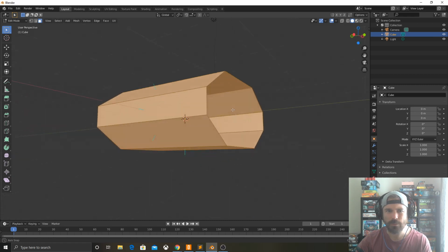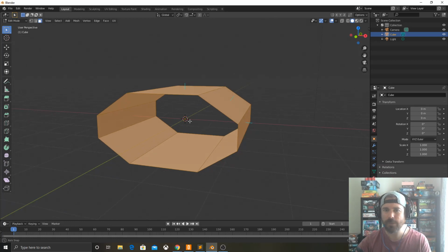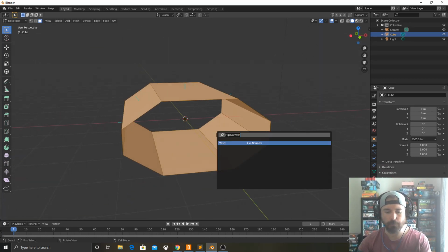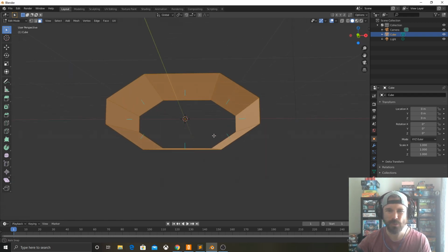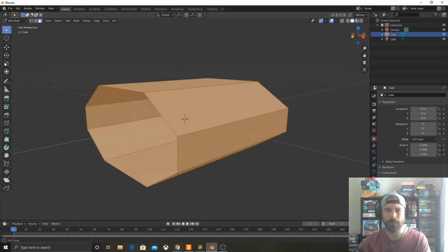You can see that that's showing the direction that the normals are facing, and also the angle that they're at. But I want to flip them. F3, flip normals, put them inside like that. So that means this is the side that's going to render in Unity or Godot.